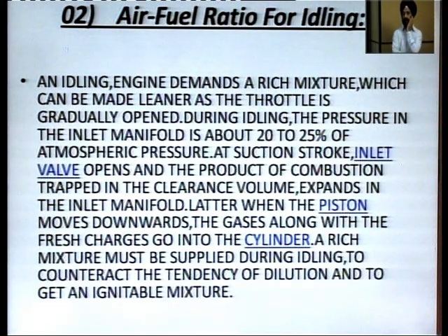So, what is idling? Idling means when we are doing nothing. When the engine is not doing anything, that is called idling. Like we have started the engine and we have not yet put the load on it. Load means if we are sitting in a car, we have not released the clutch pedal and put it in gear. It is not moving, but standing still. So, in idling, the engine demands a rich mixture. Why?